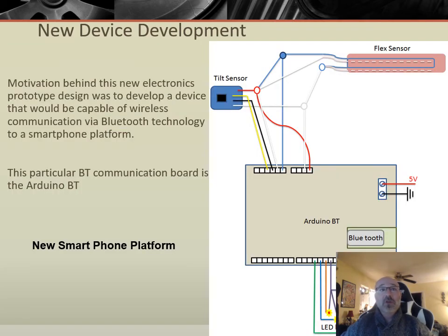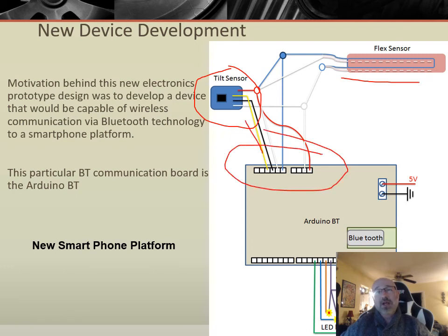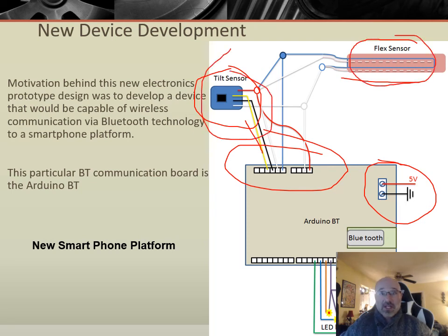So what is helpful is some of these block diagrams. So understanding, okay, this is my sensor input. This is my sensor over here. I have two sensors. They're input here. They're going in here. This is really going to help us design our control system a lot. If we understand the physical block diagram, then we can use that to make a block diagram for our actual control system. So we have everything that we need here. We have our power requirements input here. We have our flex sensor or our load dosimeter. We have our tilt sensors to let us know if we're standing or seated.